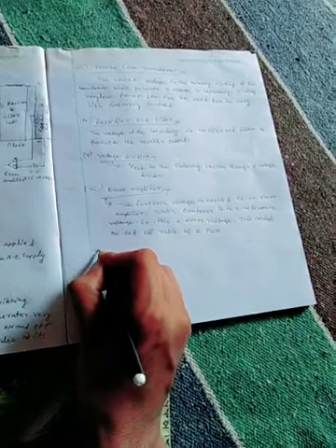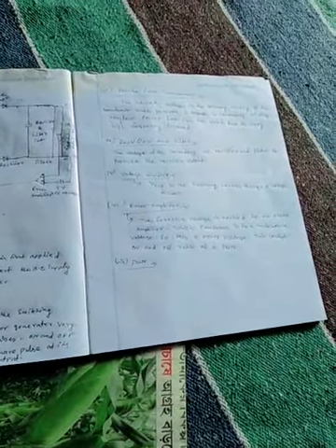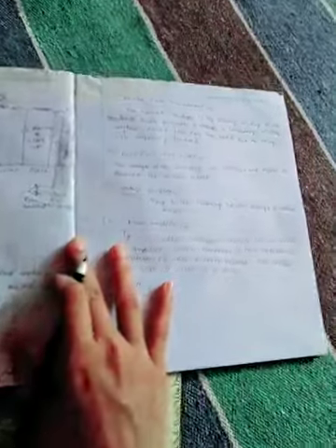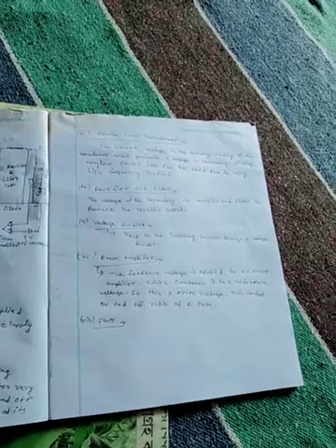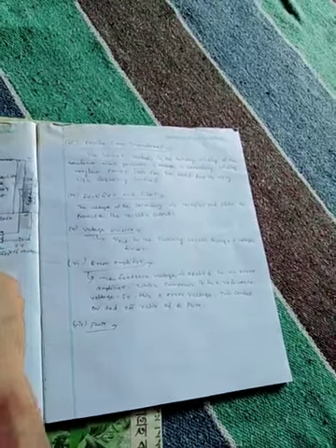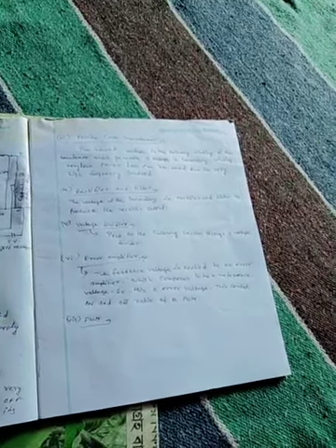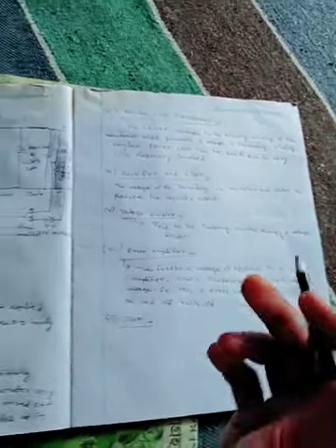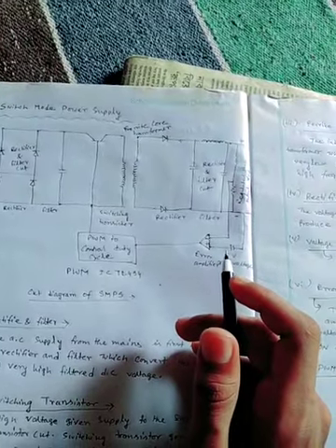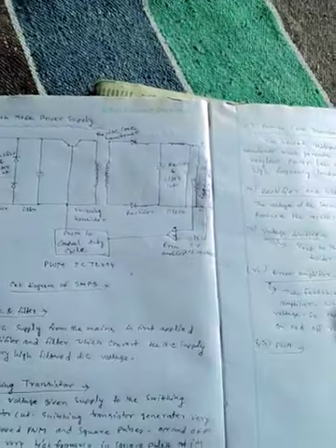The last point is PWM. PWM means the output voltage from the PWM controls the action of the switching circuit. The PWM controls the switching circuit, hence the on to off ratio controls the RMS voltage to the primary winding, resulting in the final DC output voltage.